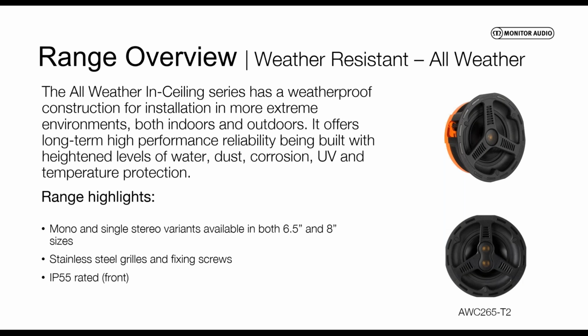We offer 2 different sizes of drive units, of mid-bass drivers, 6.5 and 8-inch. We do in this range a single stereo in-ceiling in both of those sizes as well. And yes, they come with all of the tick boxes in terms of use in an extreme environment. So stainless steel grills, uprated magnets to hold the grills in place. So if you're going to use these in marine and places like that, they haven't got the issue of grills becoming dislodged. IP rated, obviously IP55 rated, as we state on there.